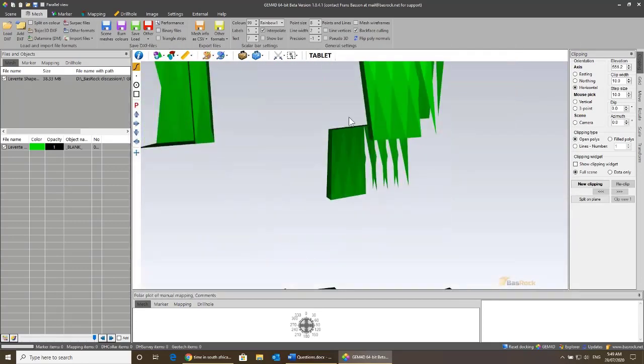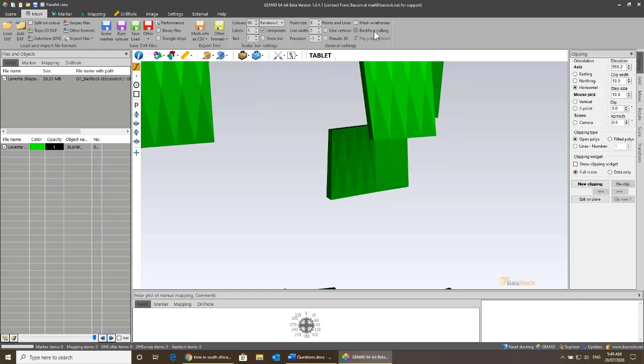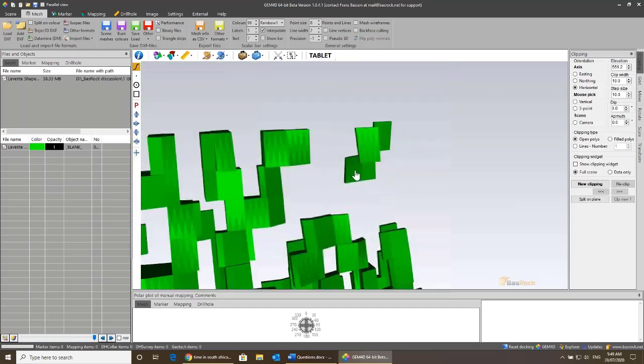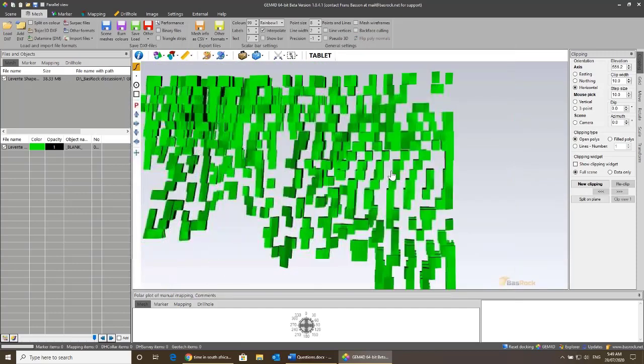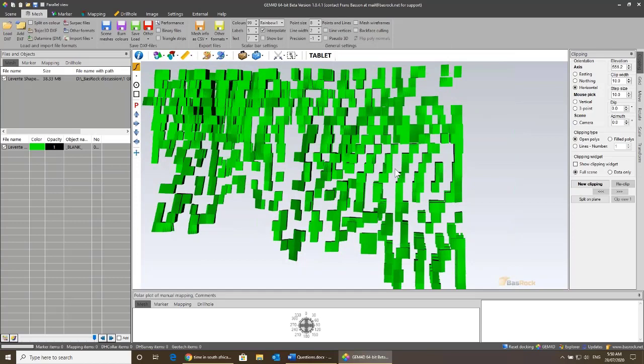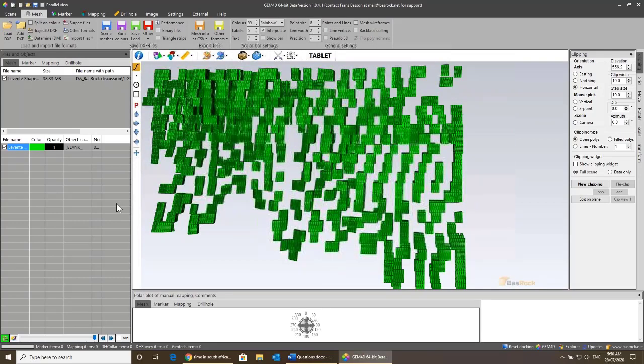If you just take one of the stopes, some polygons are showing towards you and some are showing away from you. So there's no way to take this data into Map3D at this point, because Map3D expects data to be very uniform, all the meshes and polygons showing outwards, away from the excavations and so forth. So these ones you can't use as is, although it seems like it's simple enough that you should just be able to bring it into Map3D, you cannot. Also, it's just one object. So Map3D won't be happy with it.